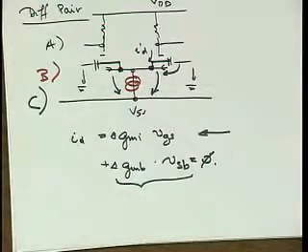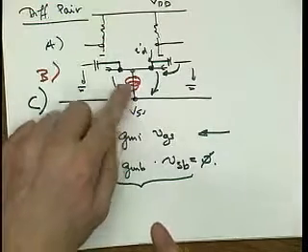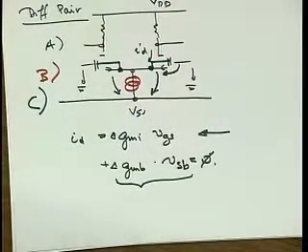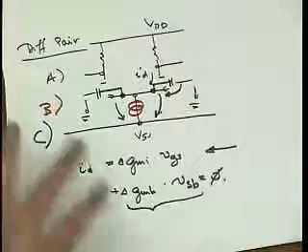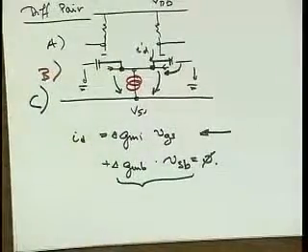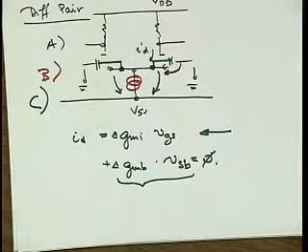Okay, so now we have an answer why we want to do all this. We have apparently 3 different solutions. Again, first one, no tail current source. Well, obviously we don't want that, right? Very poor common mode rejection ratio, and also frankly it's quite difficult to even control how much current is running in our amplifier. It depends on the input common mode voltage. Terrible, right? So solution A, clearly we don't want to use.